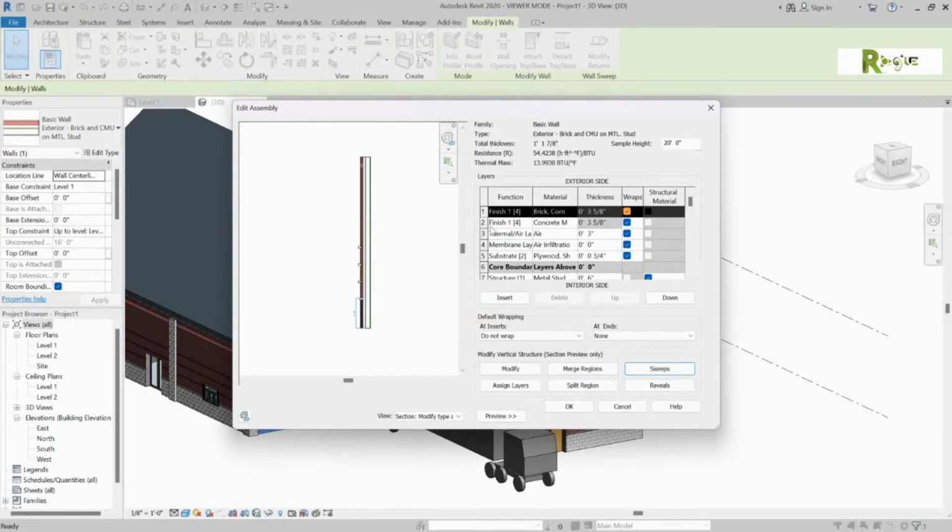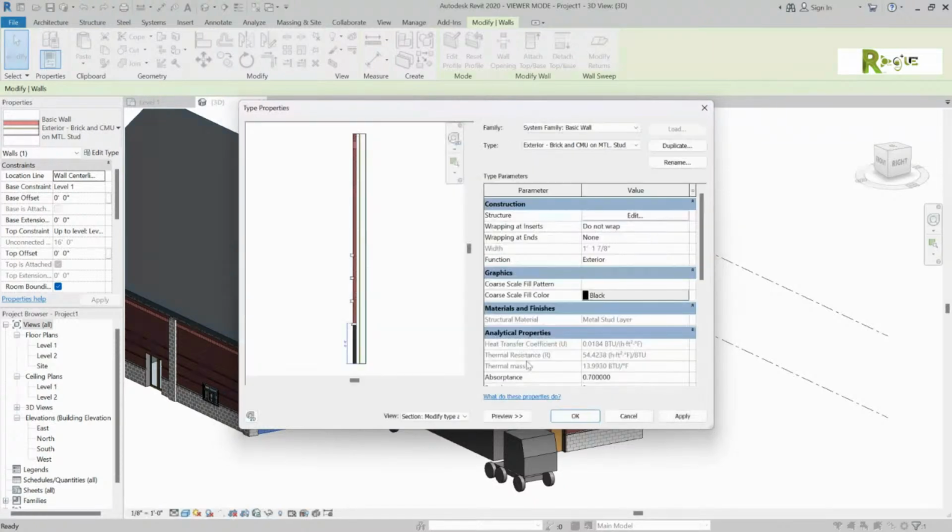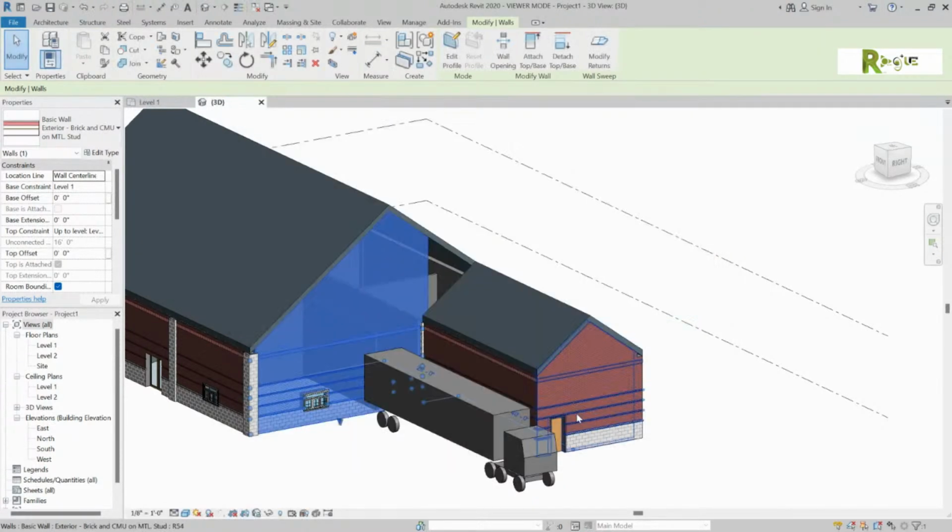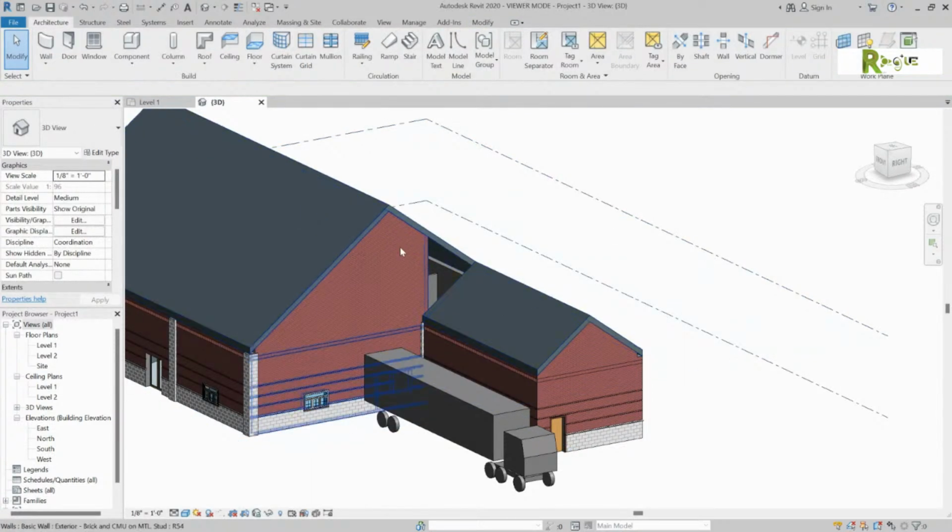But do you see how you have to go to the section view if those sweeps are built into your wall type? That's why, generally, when we go back through this in one of the later classes, we're going to show you how to put those sweeps on individually, which I've learned in my experience is the best way to do it. So go ahead and hit OK. And OK. And you see how that took that white sweep across there?